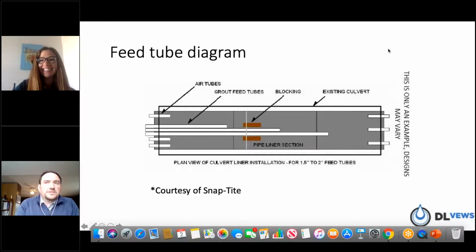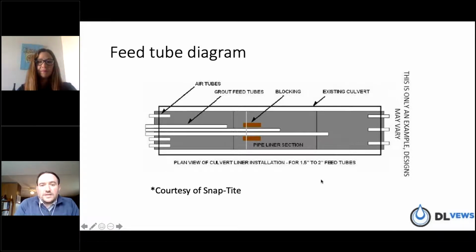Yeah, it does. And I would say, based on volume and regional market differences and things of that nature, I'm going to give a range. I've seen annular fills, actually just priced up one this morning, range from about $135 a yard in place to as much as $350 a yard in place. Normally, what the installers will do is that per yard price includes everything. So mobilizations are considered, labor's considered, prevailing wages considered, everything.